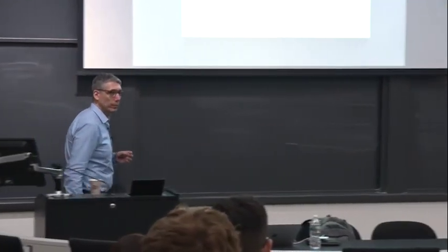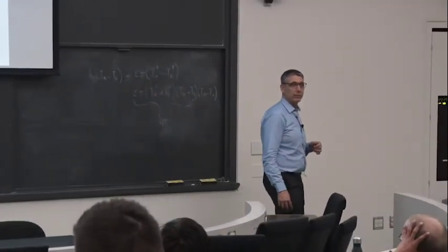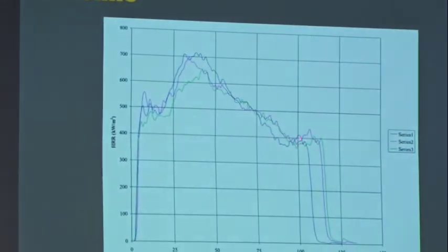Okay? So if you had to use this data to calculate the heat release rate per unit area for design purposes, which value would you use? Sorry? So Tarek says the highest. Do you agree with him? No. Why? Okay, so you've qualified it. You've said too conservative. Why is that too conservative? Because it's not representing heat release rate. So in other words, what you're telling me is that everybody will be safe here, but then you will kill everybody here, and then by the time you get here, there's nobody left.